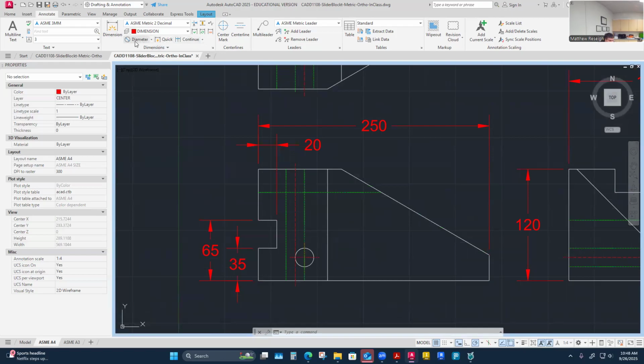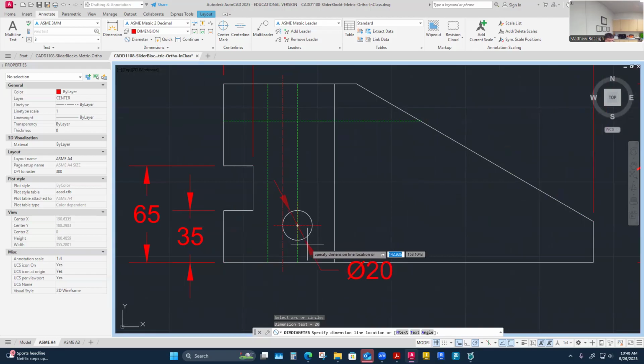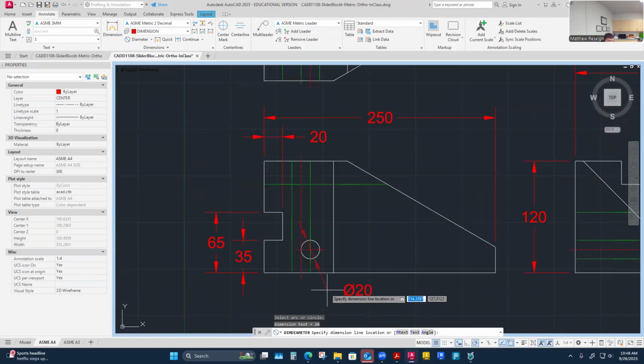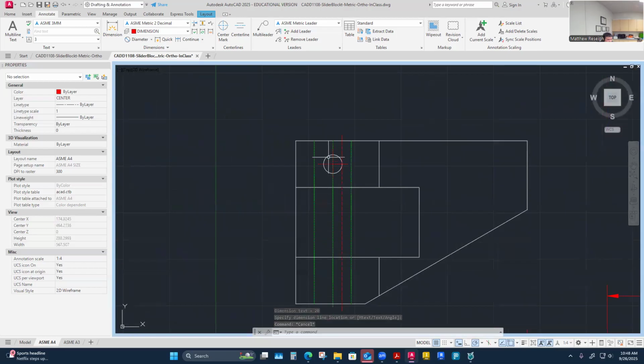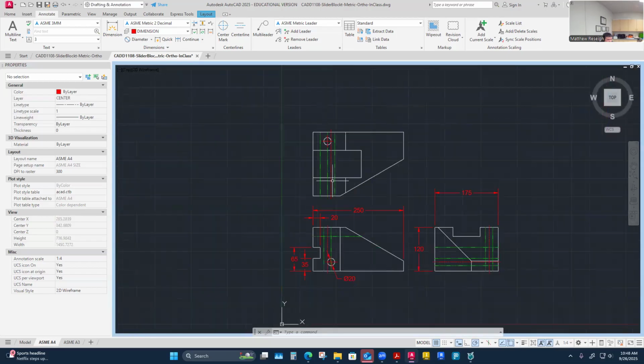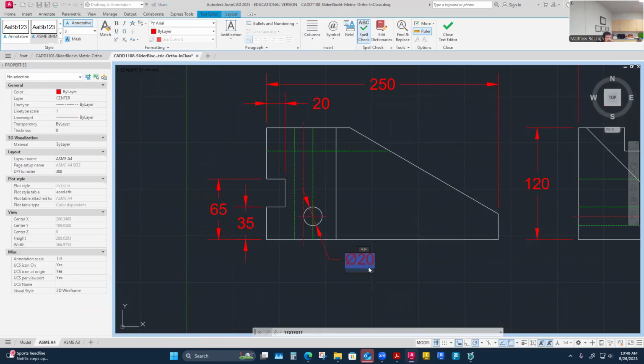So this is a diameter size. This is one that I would probably pull off and away from any other dimensions that I have. There's only one. I mean, there are two of these, but they're kind of separate features. You could say by two, and that would work, and that could infer that. But I think I will probably put its own size over here, and I think I'm going to add the words through though. That's on our other print, and so